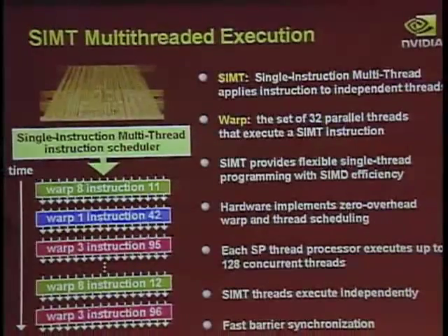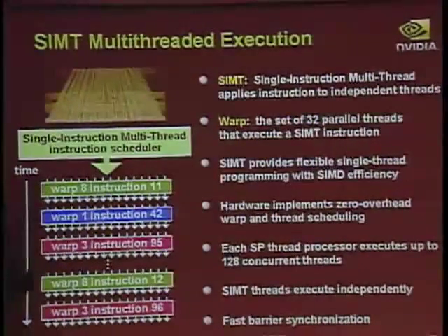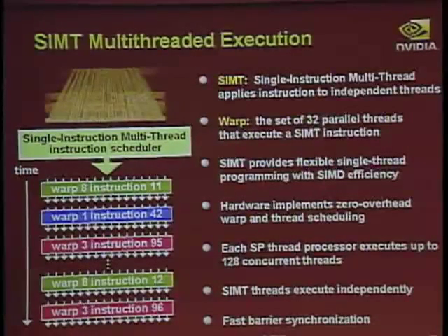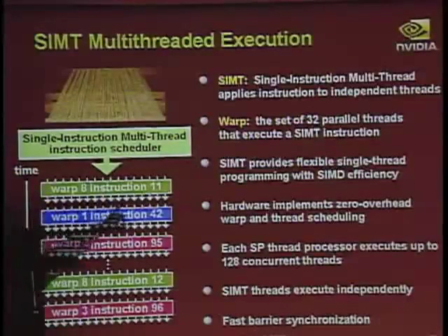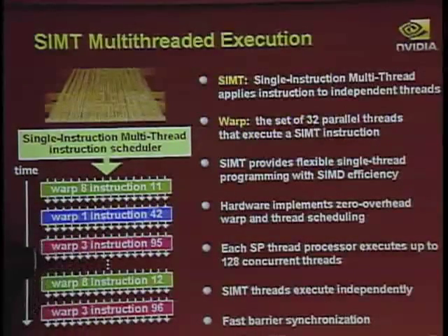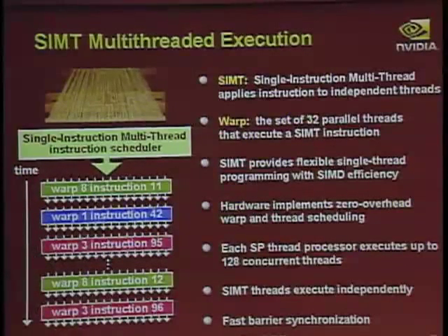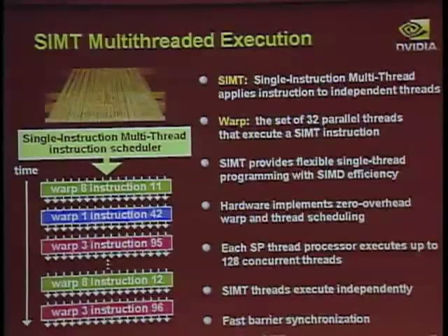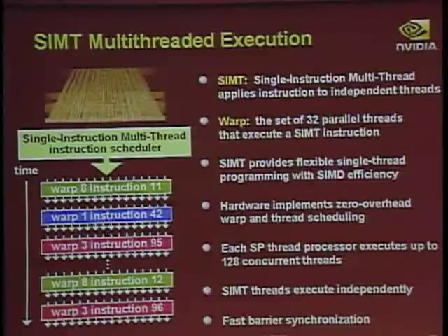But the advantage is that it allows you to write a program where you just think of writing a single thread program, and the hardware automatically looks at all these decisions. It compares all the decisions made on a conditional branch across all 32 threads, and it says, did everybody go the same way? If so, we're unanimous and we can go. No problem. If we're not, we have to diverge and push a token on the stack and remember where to come back to. Yep. This looks like the same thing when you mask certain lanes in a vector processor to have them do different things.